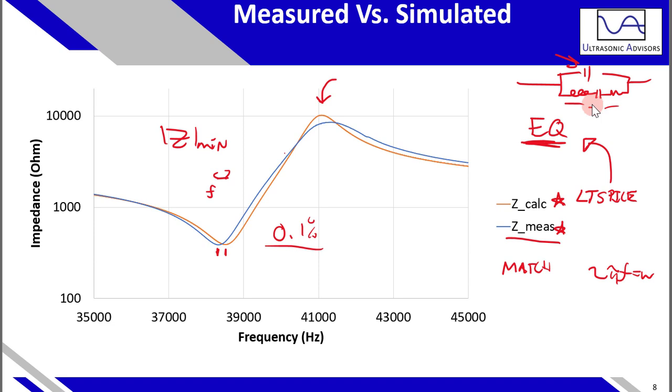So you might think that the model is not working, but actually the physical system may be nonlinear in its very nature, so you would expect some deviation because we did all of our calculations without using the anti-resonant frequency, as you notice in the equivalent circuit parameters. Now, if we had done our equivalent circuit calculation using anti-resonant frequencies, then we would have found a different set of matching. Perhaps the anti-resonance would have fit better and the resonance would fit a little bit worse, so it would get in between.